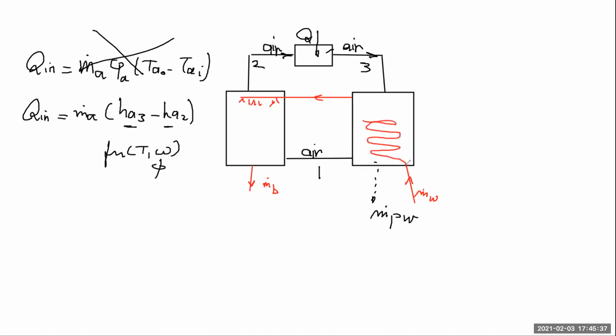This all are here. Actually, here air is coming at the maximum temperature, and it should substantially heat the water, and then the water is going to act in heating the air as it is moving up in the humidifier. When you come to the analysis, there's something that you should be aware of. We assume phi here is equal to 1, saturated condition. Saturated air leaving the humidifier. But for state number 3, phi is not equal to 1. Actually, it's much less than 1.